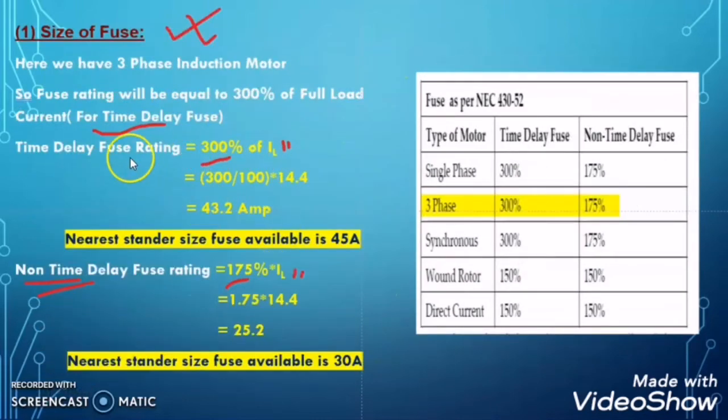Then, for a time delay fuse, the rating is 300% of full load current, so it will come to 43.2 ampere. And when the fuse is non-time delay type, the fuse rating will be 175% of full load current. So when we put in this value, we get the fuse rating for the non-time delay type fuse as 25.2 ampere. So we have to select the nearby value as per the standard selection chart.